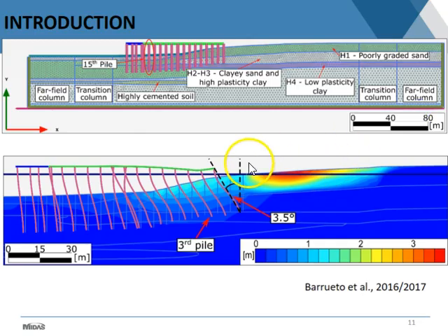And if we use the same idea, here you have the structure, you have certain material that had the tendency to liquefy and to slide laterally on top of material that didn't have such high susceptibility to liquefy. But when this happens, this soil pushes the structure and deforms it, and you can use more or less the same type of approach that I showed you with the two curves to try to get some estimates of residual lateral displacement and, of course, bending moments on the piles and some shear forces.